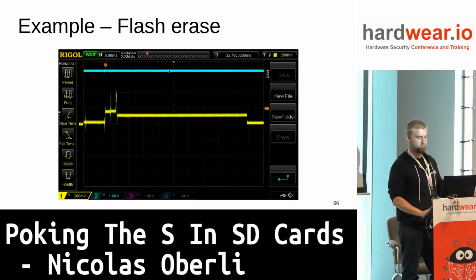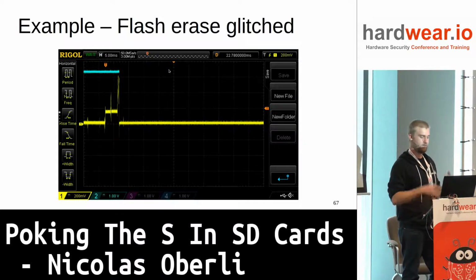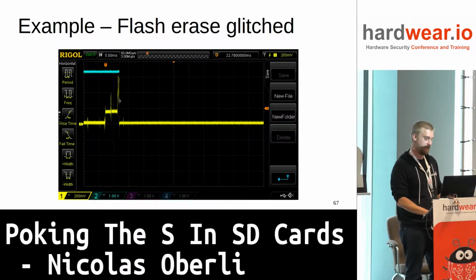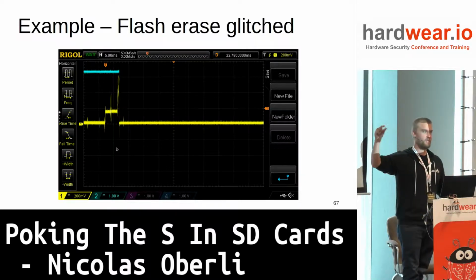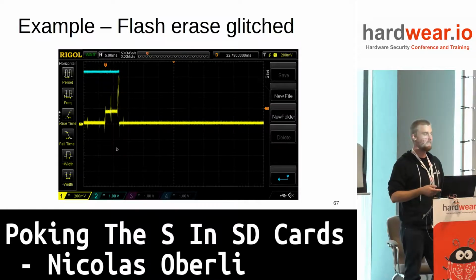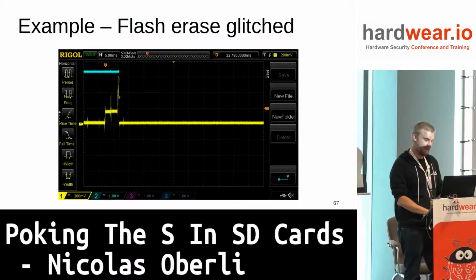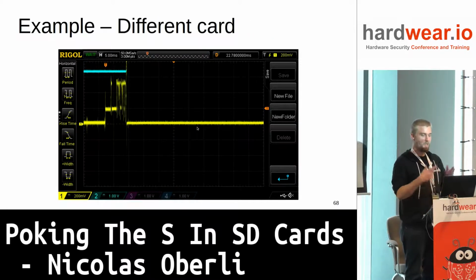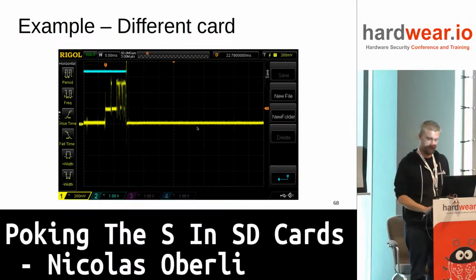So once I set up and enable the trigger, what you see is basically exactly the same at the beginning. And once there's a spike in consumption, the trigger will fire. Then the MOSFET will block the current, so the card will be shut off. You can see that as soon as the trigger is going, the consumption is nearly equal to 0. On another card, this is another example. So visually, you can see that it looks like it's working.